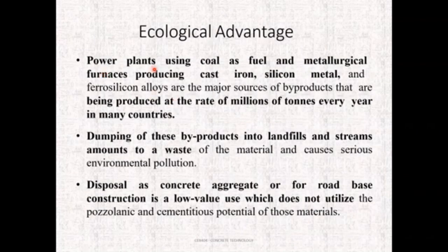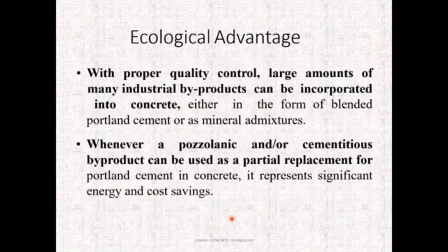The power plants using coal as a fuel are the major source of these byproducts, which are produced at a rate of millions of tons every year in many countries. Dumping of this material into landfills amounts to waste of material and will cause serious environmental pollution. Disposal as a concrete aggregate or for road-base construction is low value, and does not utilize the pozzolanic and cementitious potential of this material.